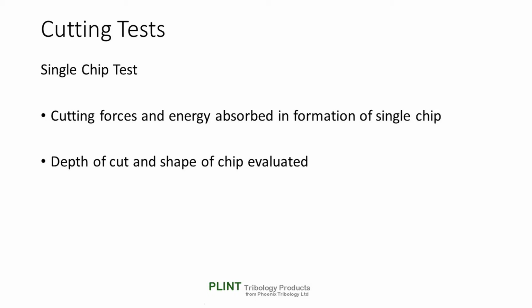A plate sample is carried in a heated bath mounted on flexures and restrained by a piezo transducer. As the pendulum swings, the tool cuts a single chip from the plate sample. The cutting force and the energy absorbed are measured, and the condition and depth of the cut and the shape of the chip evaluated.